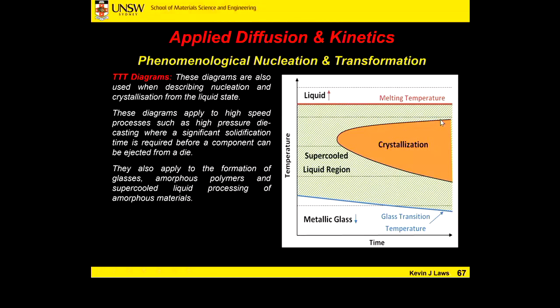And we can see here we've got this curved line. Time on this axis, don't forget. And then after some period of time, as we're dropping temperature, crystallization starts. So I'll ask the question, what's probably the event or the rate limiting step for crystallization to actually start there? If we are undercooling before crystallization starts, what's our rate limiting step? Nucleation, yeah.